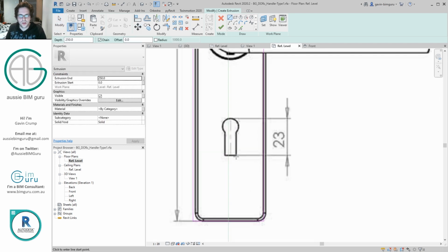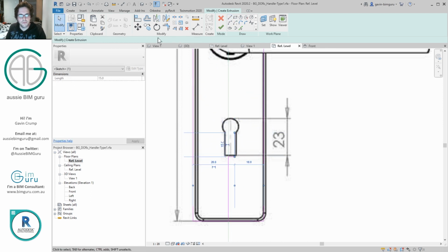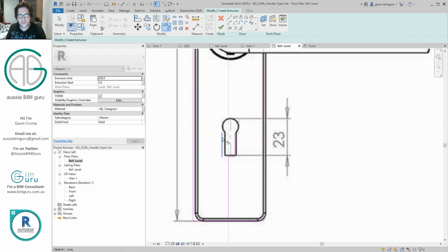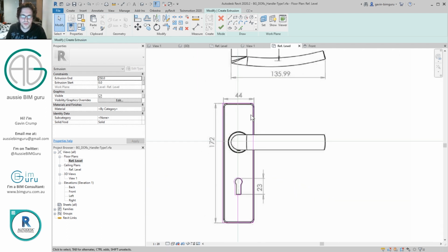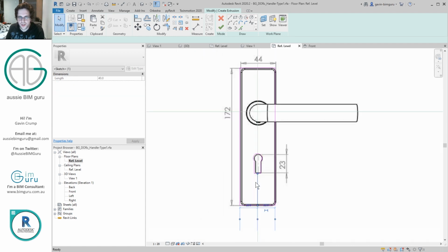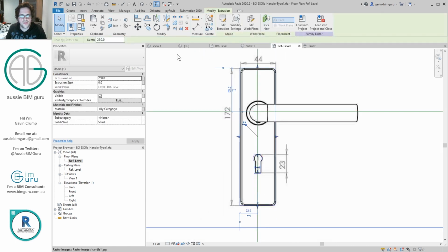I'm also going to draw the lock as well. So I'm going to go up from the middle by a whole number, so 40. I'm going to go out by 4, up by 15. In this case, I'm going to mirror this side of the lock. And then I'm just going to draw an arc. So I'm being pretty rough at this point. Very rough. I'm probably going to do a bigger size than that. I'm just being pretty nominal. You could obviously make the keyhole perfectly dimensioned, but probably no point. Anyway, at this point I need to get rid of that line that I drew for reference. And I've just drawn my faceplate, essentially.